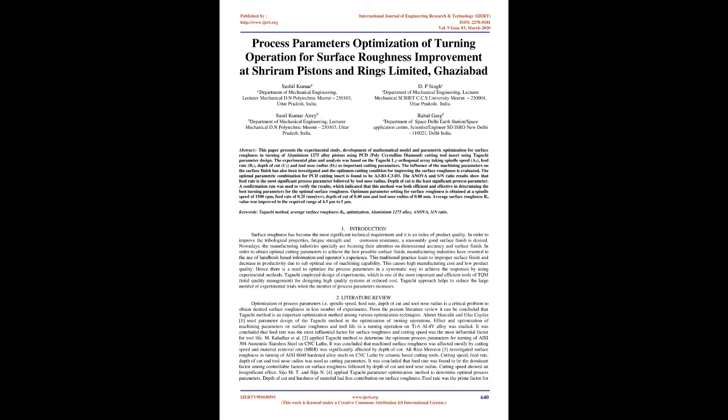aluminium 1275 alloy pistons using PCD, polycrystalline diamond, cutting tool insert using Taguchi parameter design. The experimental plan and analysis was based on the Taguchi L27 orthogonal array taking spindle speed, A3, feed rate, B1, depth of cut, C3, and tool nose radius, D3, as important cutting parameters.